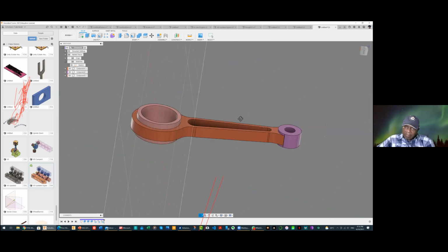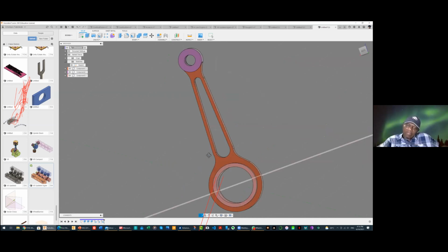Okay, so that's it. So you can follow the instruction and take the dimensions. These dimensions are not particularly good. Take the dimensions and follow as much as possible. You should be able to do this very easily. So you can see using constraints, making sure something is horizontal, making sure something is vertical, making sure something is symmetrical. All of those things are controlled by the constraints in the sketch. You don't try to use your eye to gauge anything. Let the computer do the calculation by itself for you.